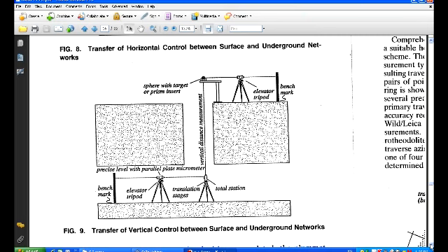Now the limitations on this process would be the limitations that there would be on distance measurement, and it's usually electro-optical, so that means there would have to be a reasonably clear line of sight to be able to have the radiation propagate through. There would also have to be a situation, as illustrated here, where the instrument is well supported, and remembering that in many instances this type of determination is a millimeter or better.